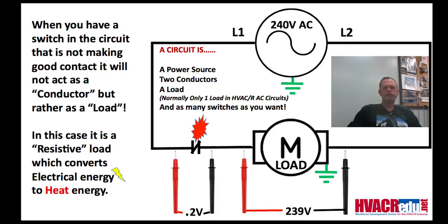But when you have a motor turning and you start dropping the voltage, the load on the motor increases because the motor cannot do the work that it was designed to do. The wattage, i.e. the work of the motor, is not able to meet the demand of the work. So the motor is going to start to get hot. When it starts to get hot, the amperage is going to go up. The more the amperage goes up, the hotter the motor gets. The hotter the motor gets, the more the amperage goes up. Pretty soon you have a burned out motor. That insulation can only take so much. Does that answer your question?